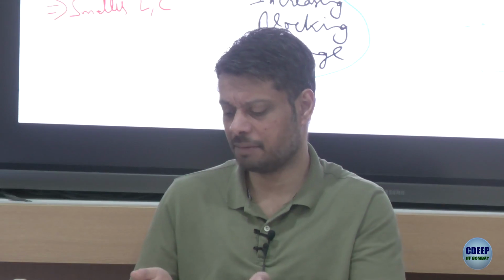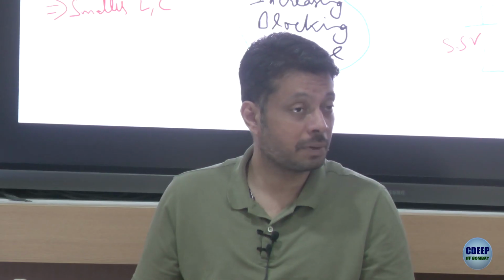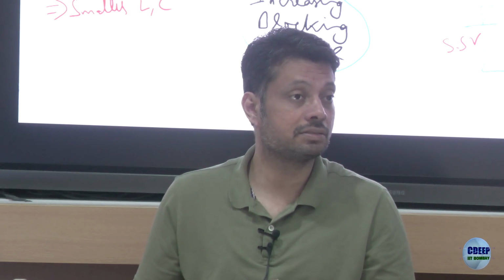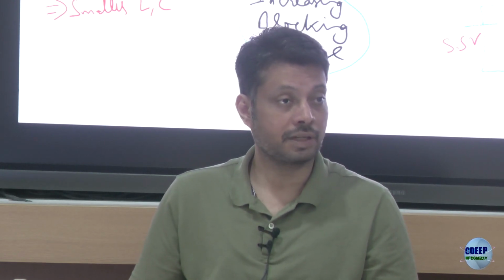Okay, the use case is the same. You have a supply of 5.5 volts and you want to generate 3 volts to charge your battery, let's say. So now what? You want to charge a 3 volt battery from there. Would you do switching at 1 megahertz, 100 kilohertz, or 10 kilohertz? 1 megahertz. Okay.